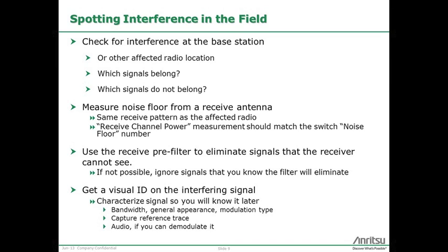And then it's a good idea to measure the noise floor using a receive antenna. Ideally, the same antenna as the radio, if there's a test port, or something with a similar pattern. And check the receive channel power. That should be the same as a noise floor number from switch statistics, if you've got those.